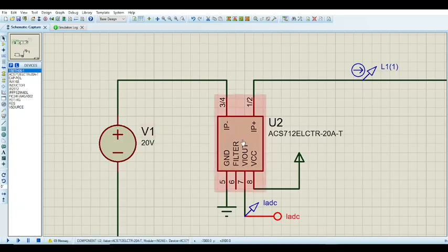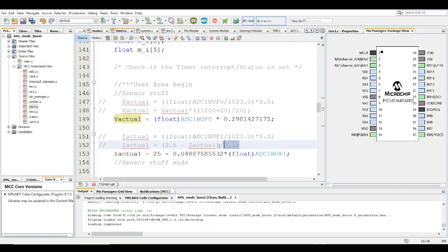If you connect it in this particular configuration, then the voltage on the output is going to go lower the more current is flowing through. And if you connect it the other way, the opposite is going to happen. For those that are using MCUs, microcontrollers that have a VREF of 3.3, I recommend connecting it like this, because then you're sure it's never going to go above 2.5. But if your microcontroller goes up to 5 volts, then you can connect it however you want. Obviously, this equation will not apply to you.